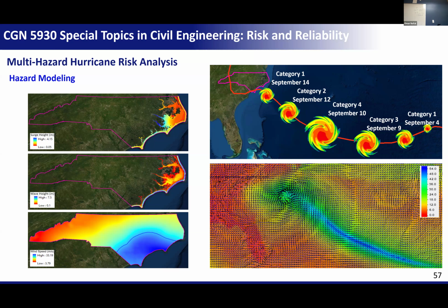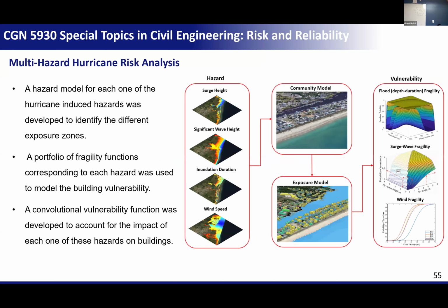The wind, basically, if a wind hits a coastal state, the whole state can feel this wind. But the areas that are close to the ocean are going to feel it more. So the hurricane hit that way. So the blue color area is the area that got exposed to a lot of wind. However, you are going to feel wind, maybe if you are here, but is this wind enough to make damage? No. So let's say that you have a fragility function that can capture the wind damage. Let's say that you have a wind of 50 miles per hour. What is the probability of exceeding damage state 1 or 2 or 3? All of them are 0. You will start to see damage when the wind speed exceeds, I don't know, 50 miles per hour.